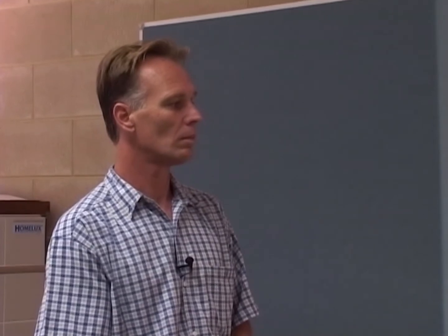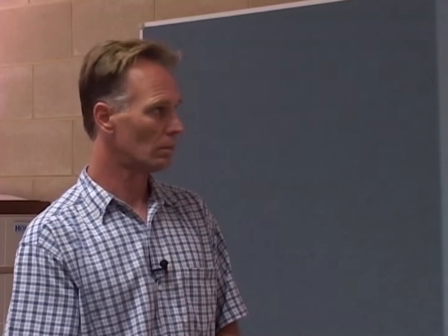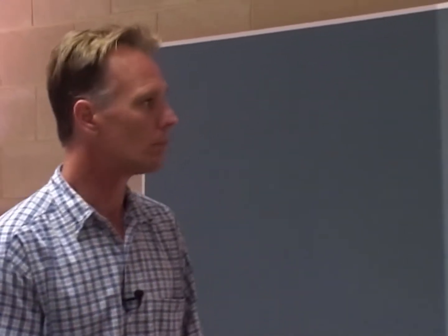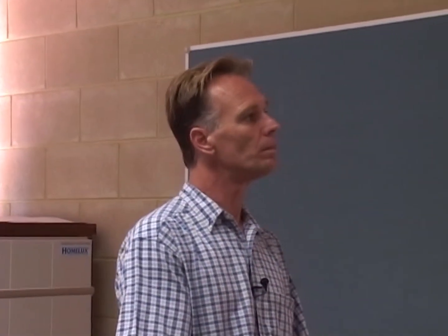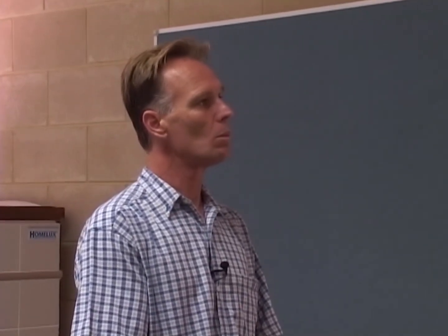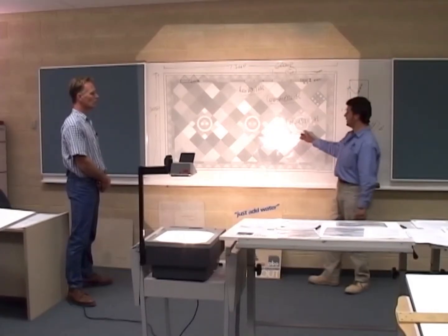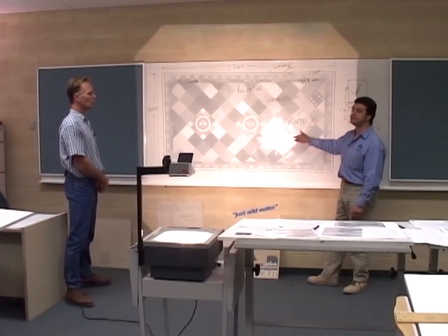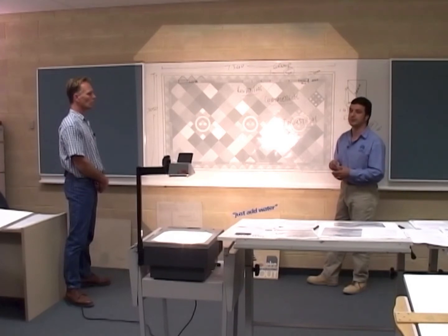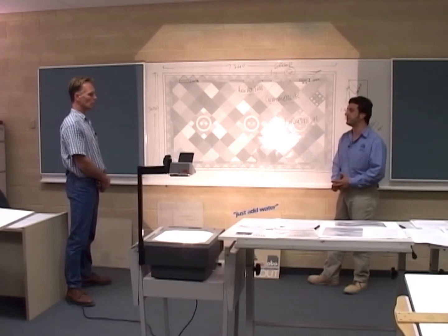You need a tile classified from group 1 to 5; you'd have to be up at group 5 plus, a tile made to cope with heavy loads and extreme traffic. If we use residential tiles in a commercial or industrial area, the glazing probably wouldn't last 12 to 18 months. You'd start to get wear over the whole floor area.